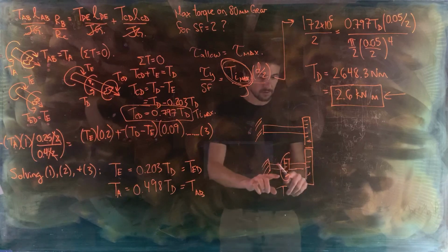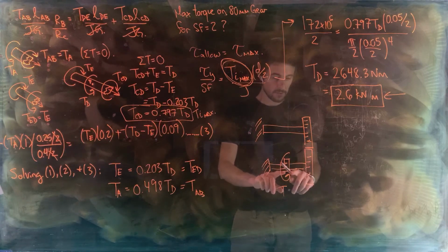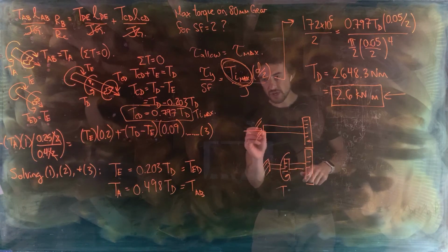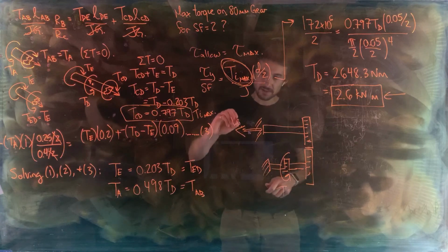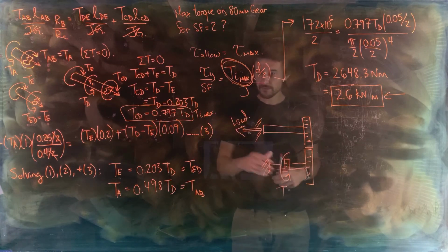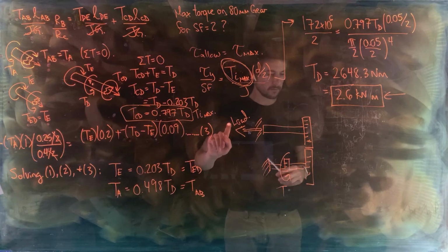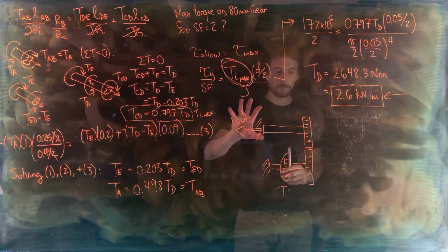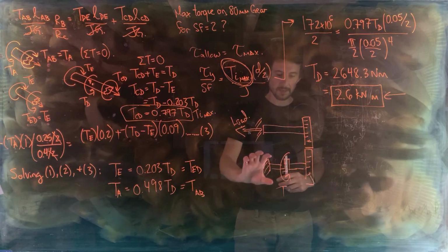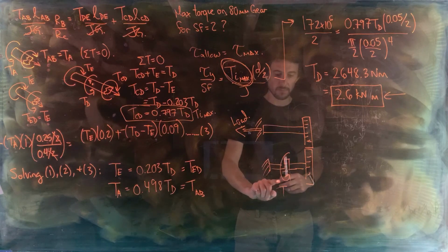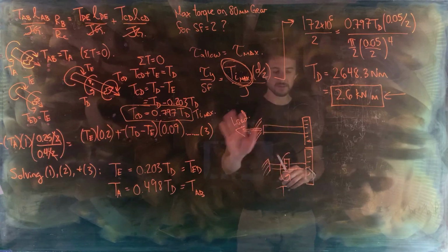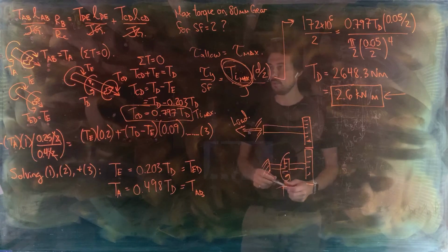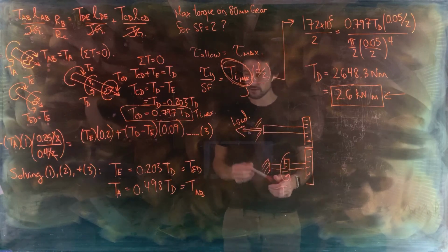This is what would happen if you had a motor driving this gear, and let's say that this shaft was normally going to drive some load like a fan or a pump or some other industrial process, and that load became jammed, and so the whole assembly stalled, and the motor was still putting input torque in, but the shafts weren't rotating. This is what this sort of problem represents, just in case you were wondering physically when would something like this be encountered.